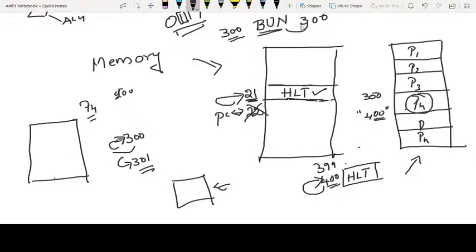That's it. You might also have a doubt: the program counter always needs to be updated, then how can the halt instruction stop updating the program counter to the next instruction rather than the current instruction? The answer is simply this. The halt instruction will be implemented by using a jump to the current instruction's address.